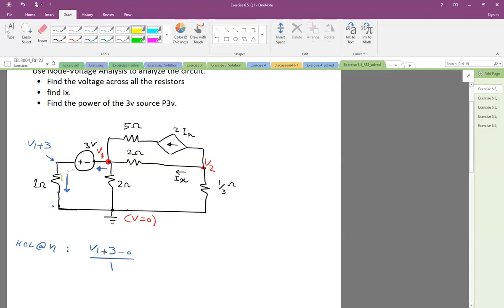The important point in this problem was to show you that when you have a voltage source here, you can use the value of the voltage, and then you can find the current through other elements, through resistors. Here there was a resistor, so I used the voltage here and the potential difference to find that current. Okay, very good. So that is that current.